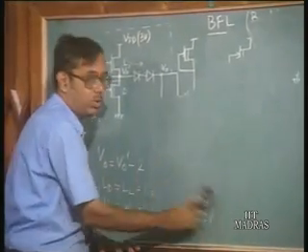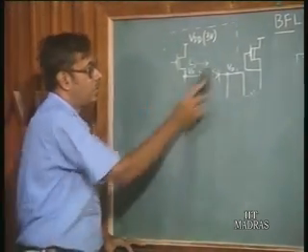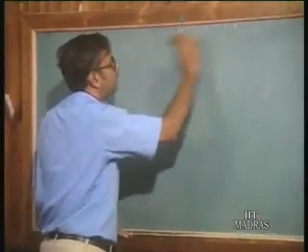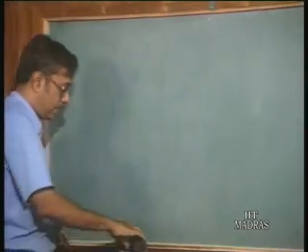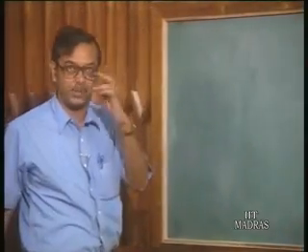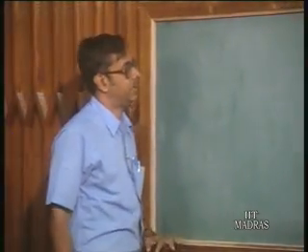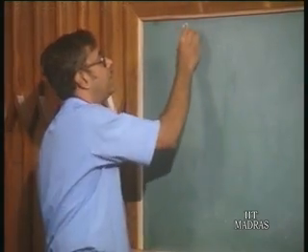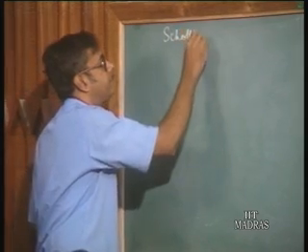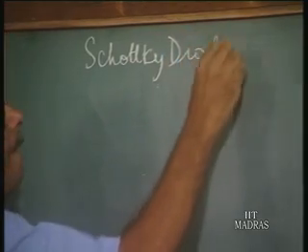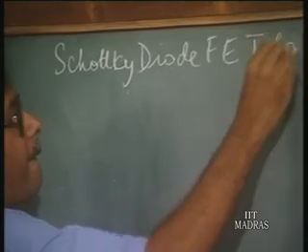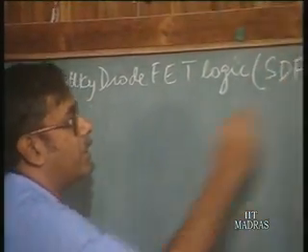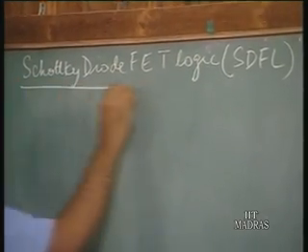I will just discuss one more logic family which also uses only depletion mode transistors, and is also quite popular. This particular logic family uses Schottky diodes for logic operation. It is called the Schottky diode FET logic, or SDFL for short. So, Schottky diode FET logic.